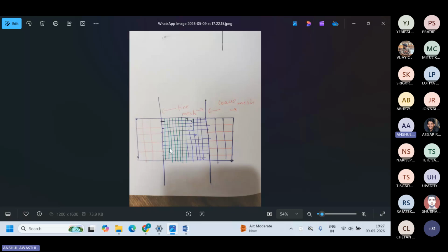If you consider a MOSFET, most of the operation takes place near the channel of the MOSFET, so you need to concentrate more near the channel. Similarly, for a PN junction diode, most of the operation takes place near the junction. So if you make the mesh finer near the junction and coarser away from the junction, it is fine. That's why I have defined one more multi-box.